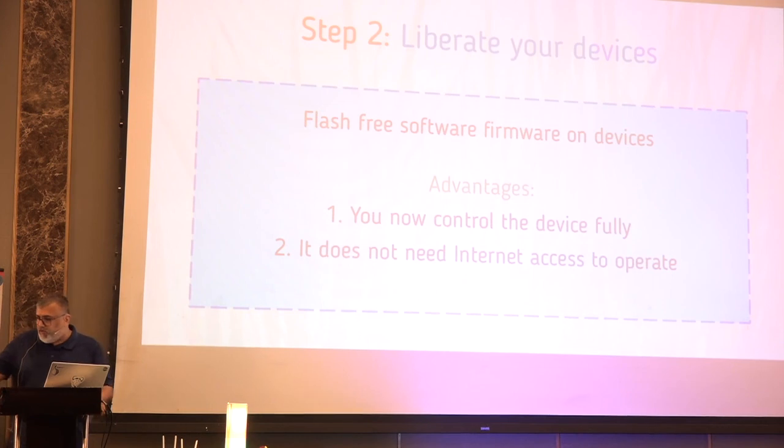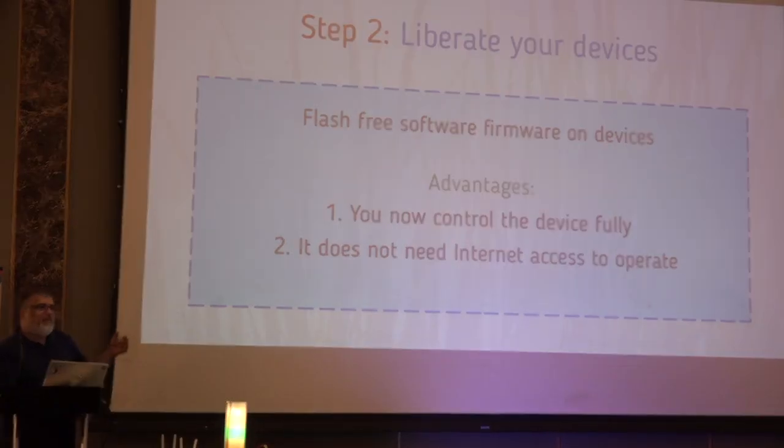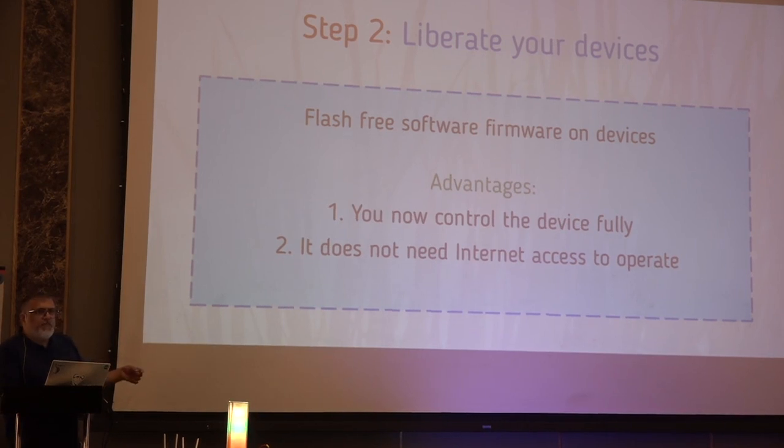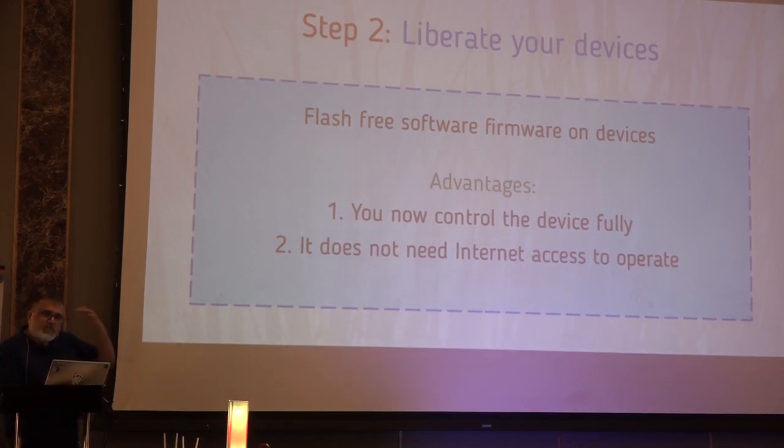So I have a lot of devices with me which are unflashed, and we can open these up as well. But what happens on these devices is that they need to have certain pins on the board to program the microcontroller in the first place, right? And fortunately, they leave those pins populated on these products when they ship it.